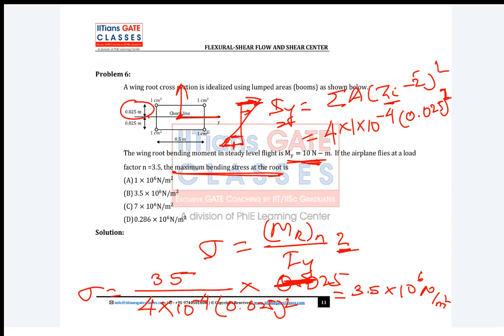Now guys, Rangarasu, have you done this question earlier? See guys, in this question, what mistake do people make? Anyone can tell? Usually they consider this wing section, with the weight acting here and lift acting here like this. Is this correct idealization?